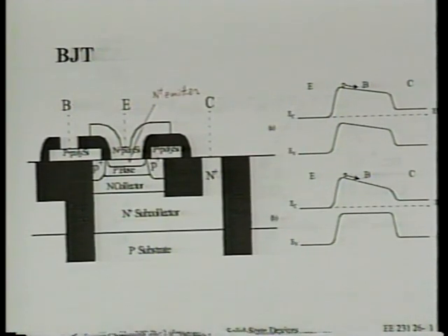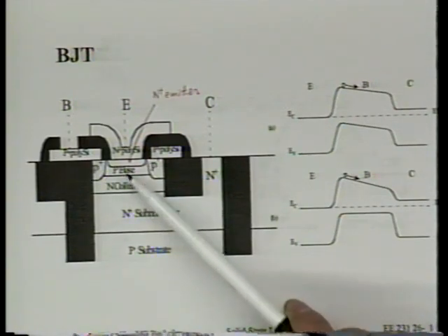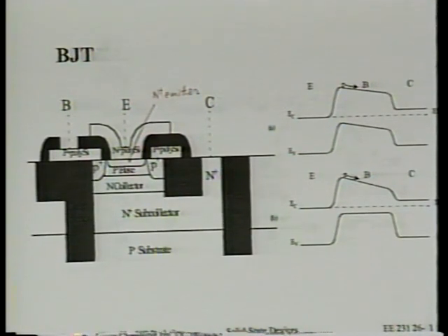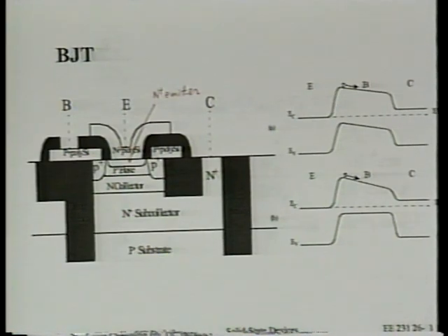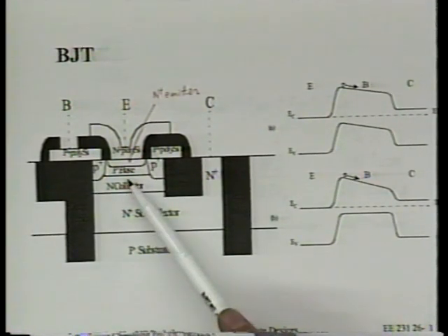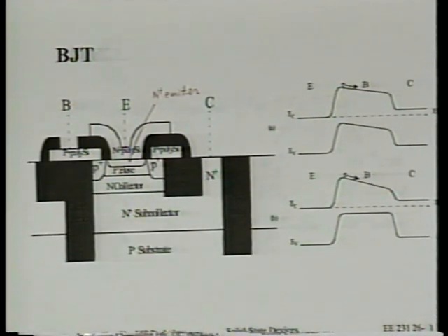A bipolar transistor has two breakdown voltages. The one that's lower, of course, truly limits us. And the lower one can be many times lower than the breakdown voltage of this junction, by the cubic root of beta, for example. So if you want a fairly decent breakdown voltage of the bipolar transistor, we had better make this PN junction breakdown voltage quite large.